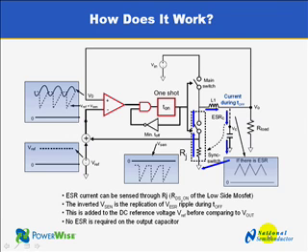So how does that emulated ripple mode work? Here you see again the block diagram of a constant on-time regulator. The blue arrows indicate the current loop during the off time. We have a current circulation through the output capacitor, the MOSFET, the inductor, and back to the output capacitor.